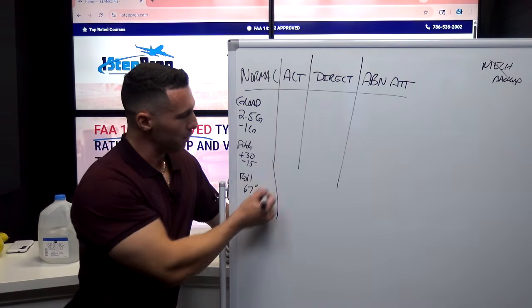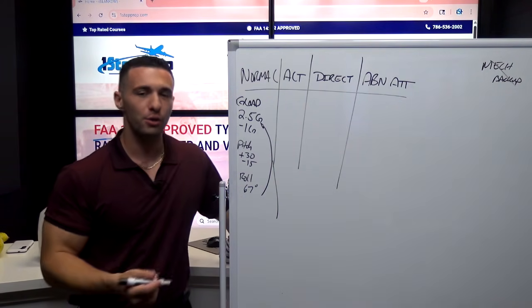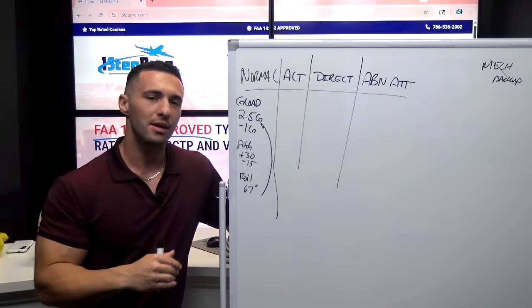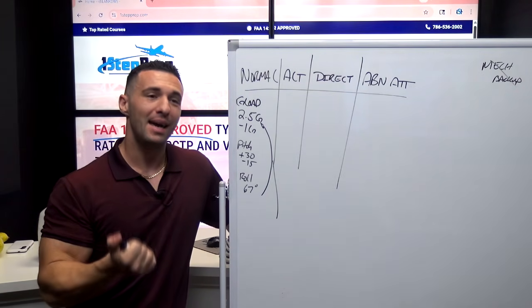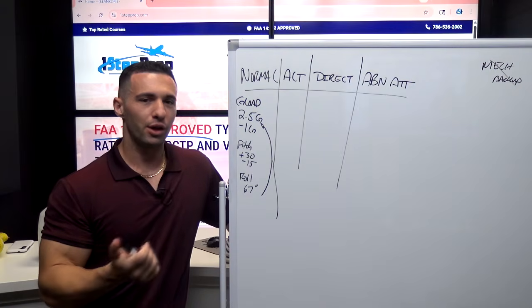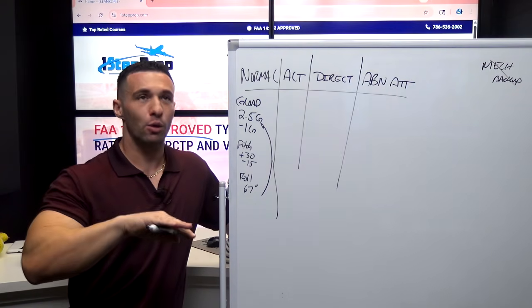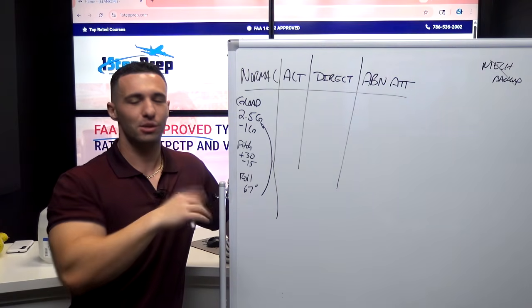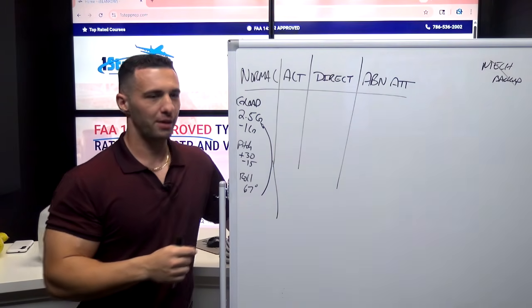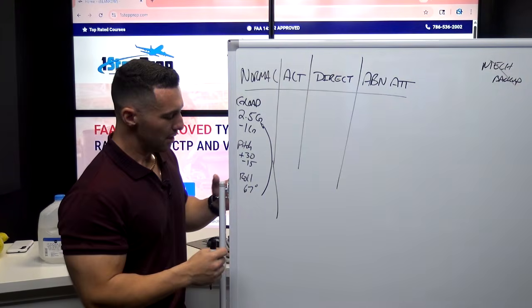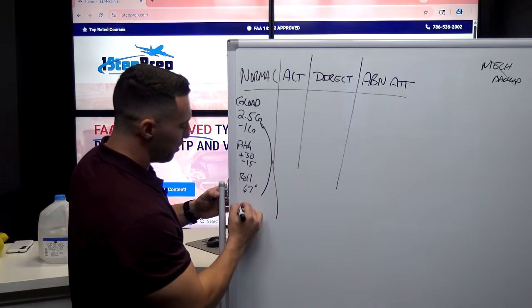And this basically relates back to the G load. So effectively, if you turn 67 degrees of bank and pull on the stick aft to maintain altitude, you're going to run up against the 2.5 G load limit. So the bank angle ties directly to another limitation, which happens to do with G load. So hopefully that makes sense. They both tie in. Apart from that, we have airspeed protection.